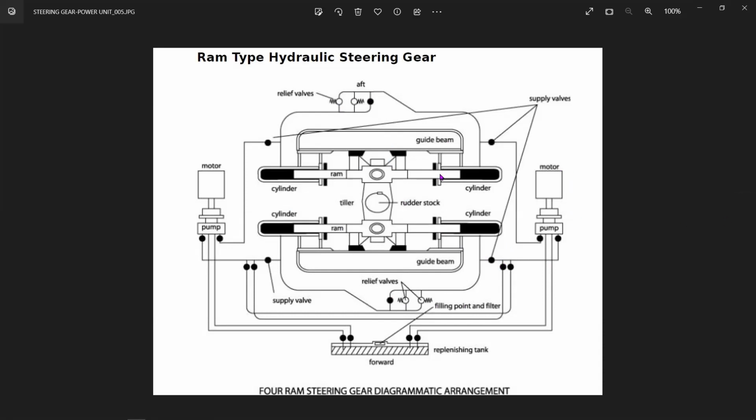But again, the idea is that there are 2 motors, both of them taking from a tank, and they are operating either together or independently, depending on the requirement. Whether both are at 100%, both can operate the entire system together, or if they require 50%, then both of them together supply the entire 100%. Means either one could be operating at 100% load if they are designed that way, or they could be at 50% load if they are operating together. It depends on that system, which we read in the rules, right?